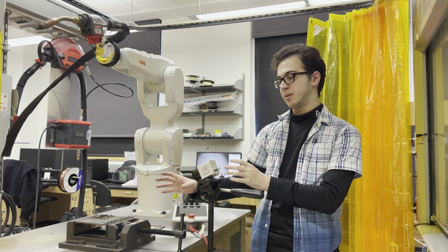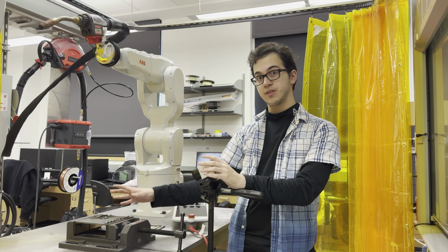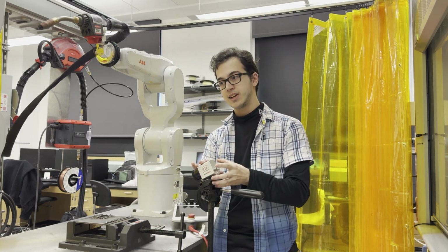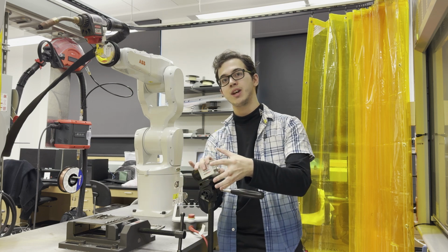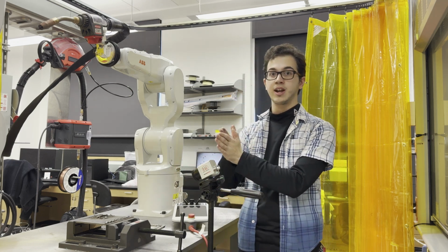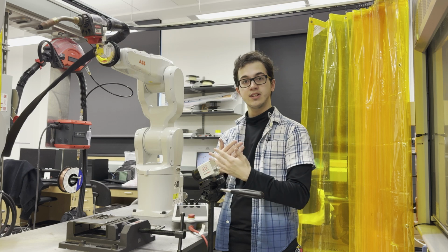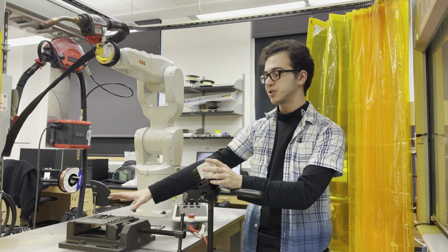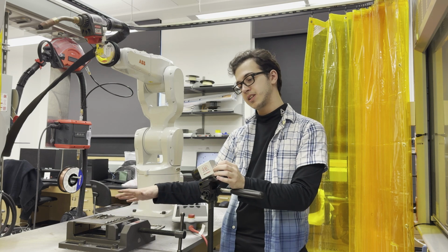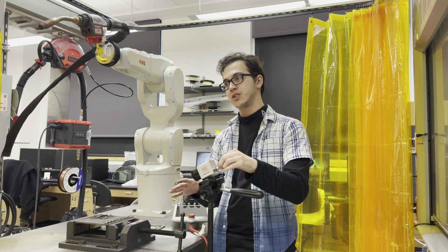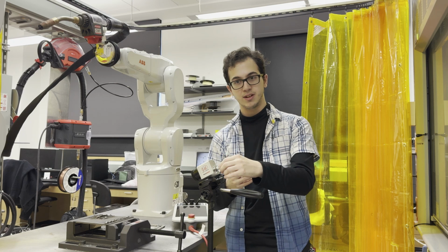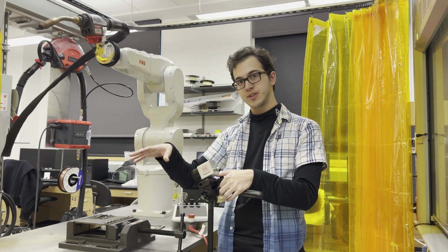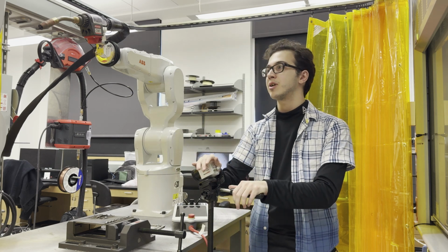It sees a thermal image, classic thermal camera look, and this data is saved into a CSV file as a frame. In the same way a camera has individual frames, we capture individual frames of the welding process, but those frames aren't just color pixels, they're more so temperature pixels. And we save that individual frame as a CSV for data processing later.